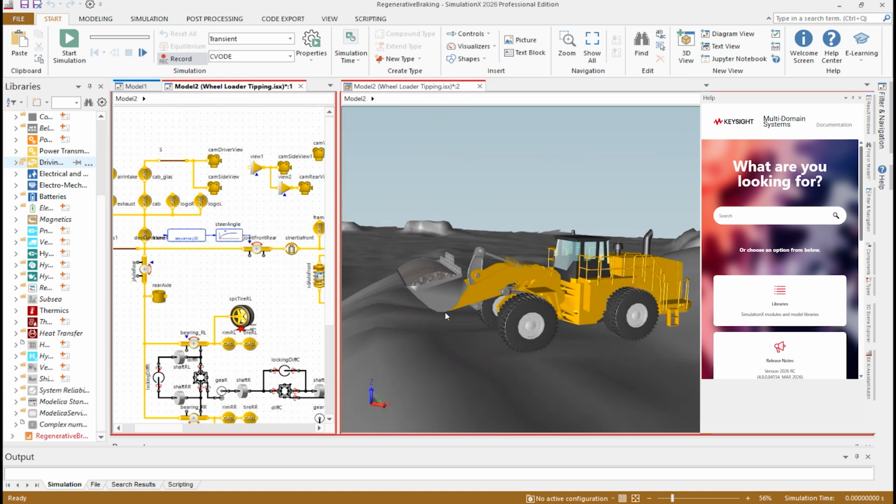It can mean we change the design of the machine, or if we say no, we cannot avoid it through design, then we should change the way the machine is operating. So we should prevent the driver from going into such a scenario by limiting the load, or limiting the gradient which you go downhill, maybe having a combination of both, saying, okay, with this load, this gradient is permitted.